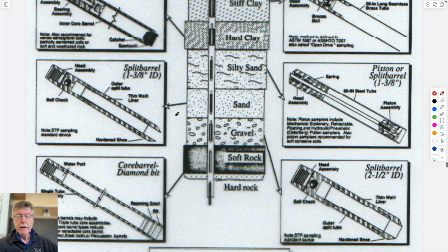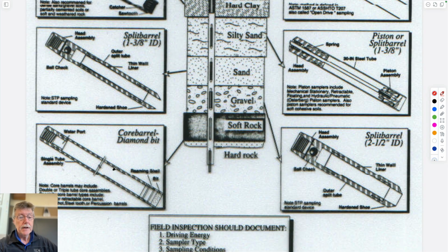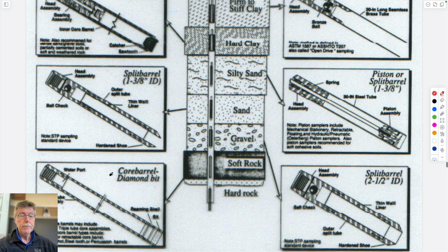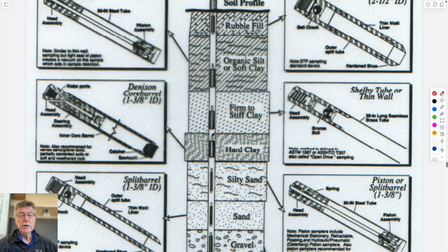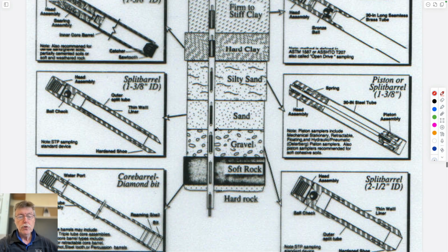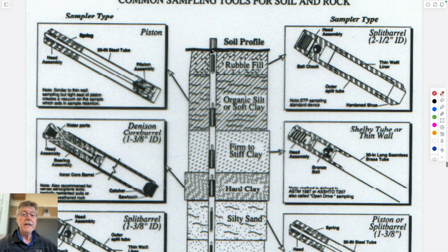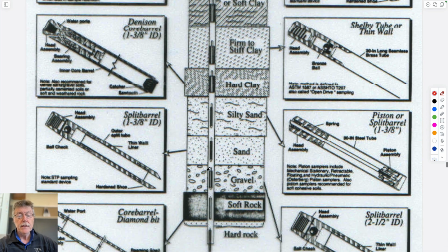If we have diamond drilling, which would be this, we don't need to take any samples because the very act of advancing gives us an actual sample inside the tool, which is then raised to the surface, either by pulling all the drill steel up to the surface and breaking it open, or preferably bringing the core tube, which is present right at the base, up through the remaining line up to the surface, breaking it open, taking the core out, and while you're doing that, putting the other core barrel down and then just keeping on drilling while you're breaking the other stuff open.